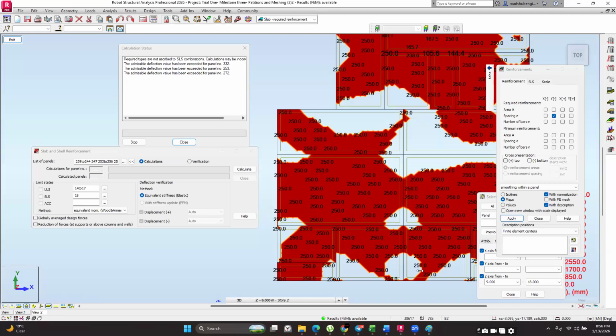What you can do is, remember this is a solid slab. If your solid slabs are going to depths of 200 mm, probably 200 mm on the maximum side, if you start going above 200 mm, I would recommend you look at different slab systems. If you're designing your slabs and they start going above depths of 200 mm, you can start looking at different slab systems.